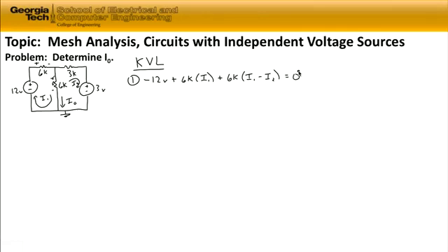So our first equation has two unknowns, loop current 1 and loop current 2. Let's look at loop 2. Ultimately, if we can find another independent equation which has I1 and I2 in it, then we can solve these equations simultaneously. We have two equations and two unknowns. So let's do that. Let's start with the lower left-hand corner of loop 2, come up through the 6K resistor, the 3K, and then the voltage source on the right-hand side of the circuit, and back to the beginning.